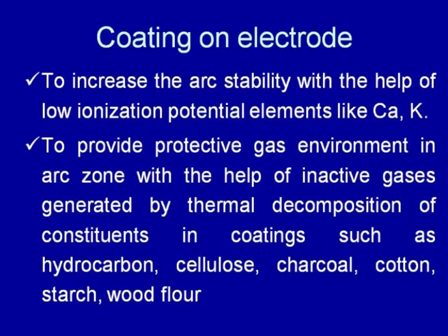So, when these decompose under the influence of the welding arc heat, they provide the protective gases to protect the weld pool. And these are the inactive gases, these are not the inert gases, but they help to protect the weld pool from the atmospheric contamination. However, the protection is not found to be very effective.